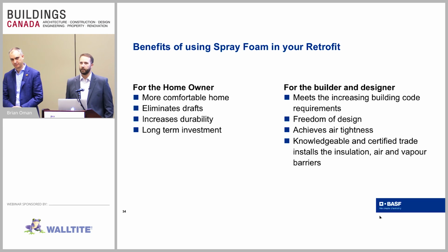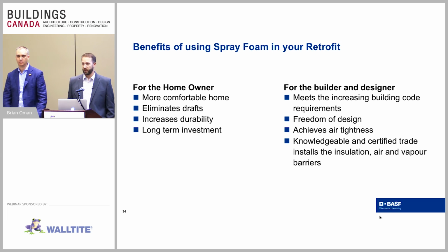So, yes and no. The spray foam itself can act as the vapor barrier, and due to its permeance level, it will mitigate the moisture as it's trying to permeate through. The bigger thing becomes the need for drainage and now the requirements for radon mitigation.